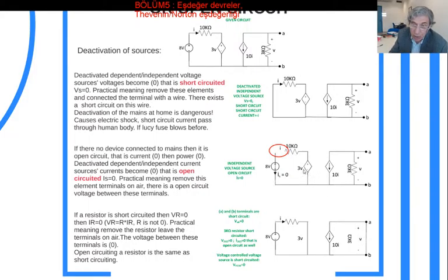But there is a dependent source here, whose voltage depends on the voltage between A and B. I already made this voltage equal to zero. Therefore, this dependent voltage source voltage is zero as well. So I put a short circuit here. So if somebody says that the A and B terminals are going to be short circuited, three actions happen here.